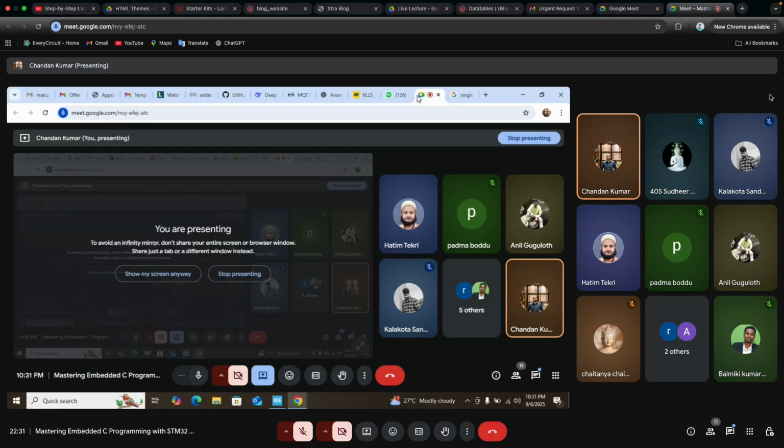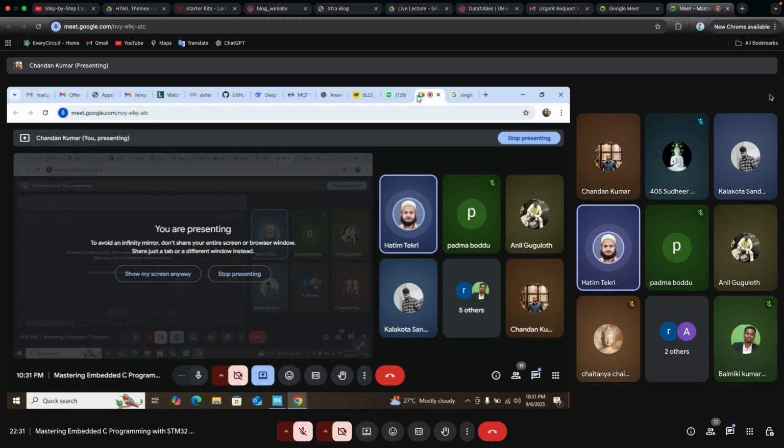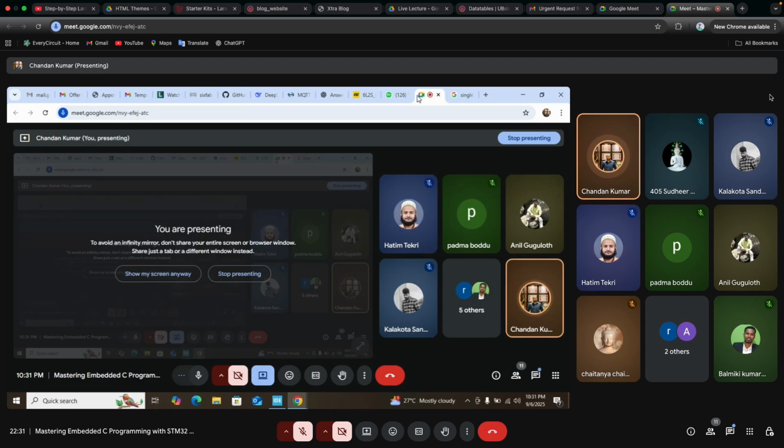It means the transaction of a new communication is starting here. So for that, it's called a start condition. Any doubt, or am I clear? Yeah, it's great. So start condition means the data transferring will start now. At that time, the data pin will be transiting from high to low, and the clock pin will be high.